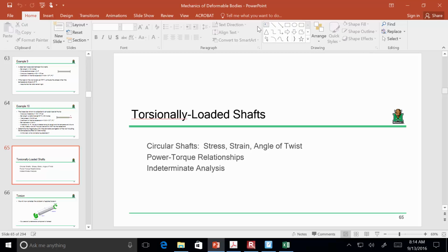Okay. Weight of the load is increased by 9 kips to 21 kips. What percent of the total load is now carried by the middle cable? Well, for part A, unless I'm reading this incorrectly, it would still just be 33%. The stresses would be different.